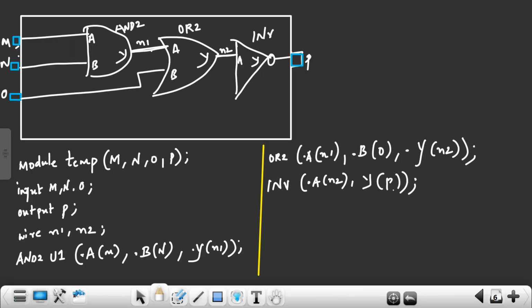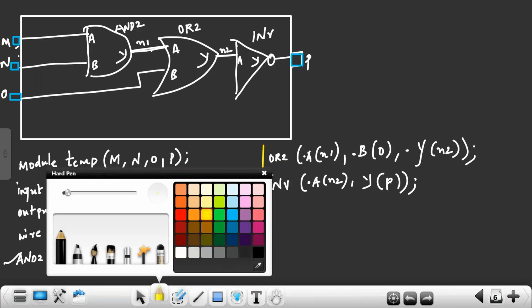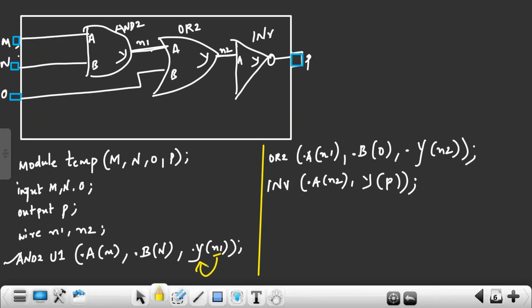So this is called gates and their connections. Only this information should be present in the netlist. See, the connection is maintained here. Net N1 is connecting to the output pin of the AND gate, and the same net N1 is connecting to the input pin of the OR gate. Then the meaning is that the output of the AND gate is connected to the input of the OR gate. Even if I don't give the schematic, my tool can understand from this.